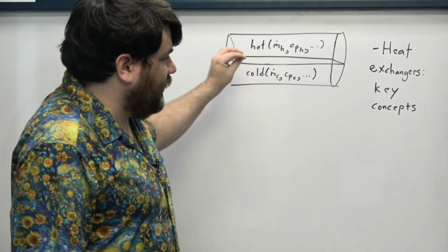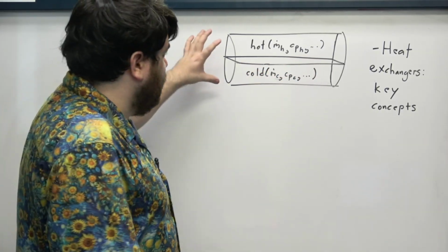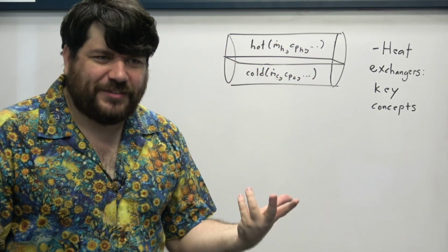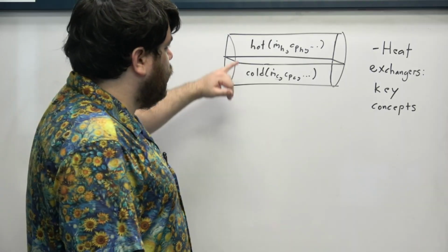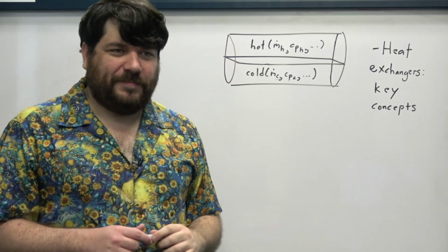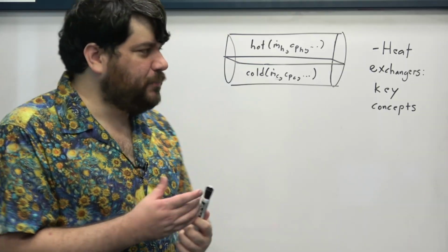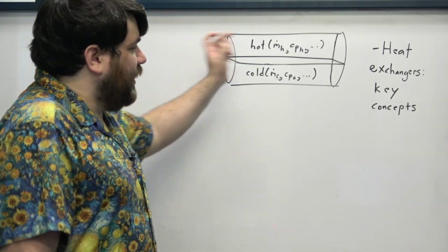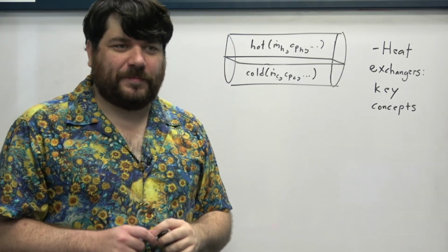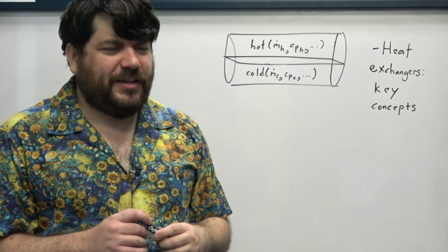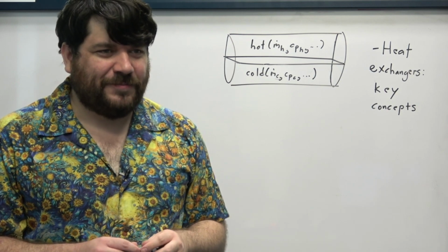And the characteristics of the way that these two fluids flow inside of the system, the geometry associated with this separating barrier, the geometry of the pipe or duct that contains them, all of this stuff affects the heat transfer that occurs between the hot liquid and the cold liquid, okay? In addition, something as simple as altering the directions in which these liquids flow can significantly impact how effective the heat transfer between those two liquids is in this system.